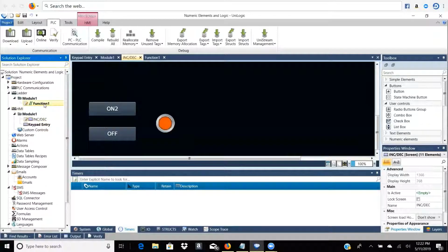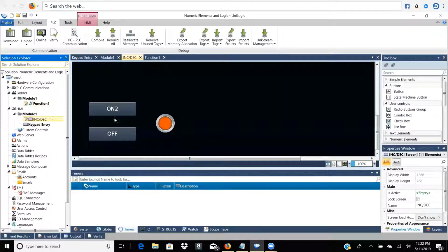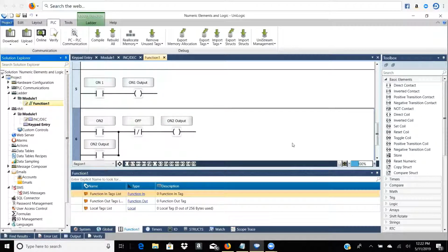When it goes on, this contactor is energized, the coil is energized, and it turns on this contactor, and in the process it will keep this light on until we turn this off. Then this light will go off. So that is it. This is how you can create a simple switching circuit that will keep holding on until you power it off using this normally closed contactor. Thank you.